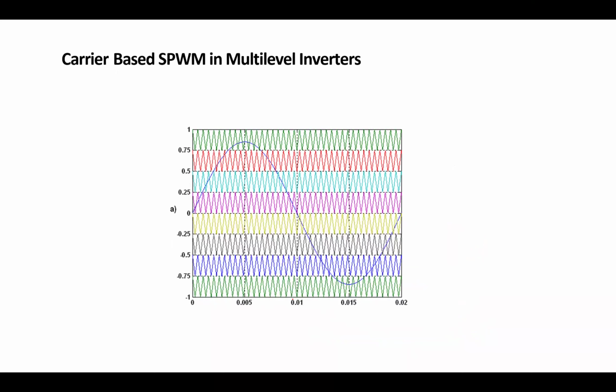Now, in a multi-level inverter, remember, we have a bunch of cascaded inverters, full bridge or half bridge, doesn't matter, that overall create the whole signal. Now that the whole signal should be divided between the several modules in our inverters, that per unit part that we talked about, we have to normalize it again.